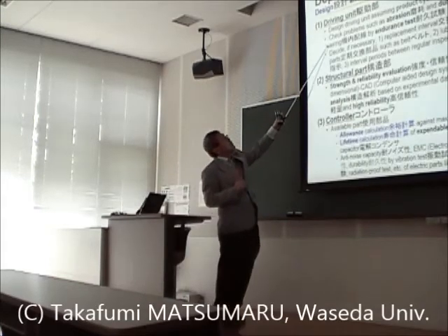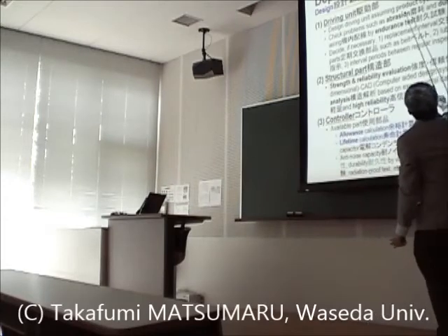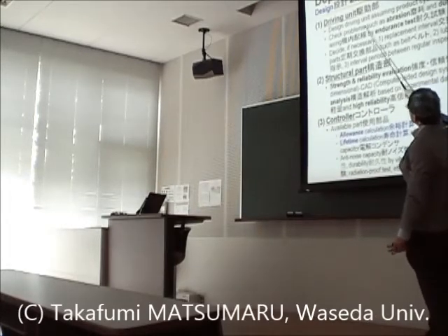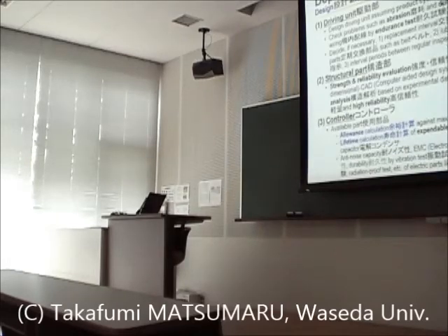This is an example in the case of the industrial robot driving unit. For the driving unit, we design assuming the product cycle, and check items such as abrasion and durability by endurance tests. We also have to think about regular inspection and repair, replacement intervals for periodic replacement parts such as the timing belt, and lubrication instructions, pouring oil for the driving part and so on.